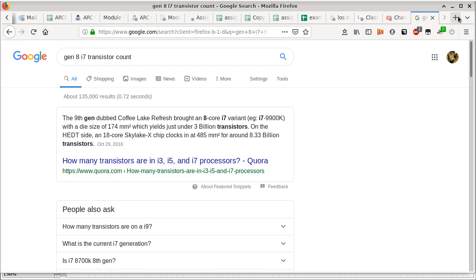Now we have more variables, right? Because between wafers, the base material or the substrate material can come from a different batch. So this batch of silicon may have more or less impurity than the next batch of silicon substrate. So there you have even more variables between wafers. But even on the same wafer, you can still have a lot of variables. Is that good? Okay. All right.